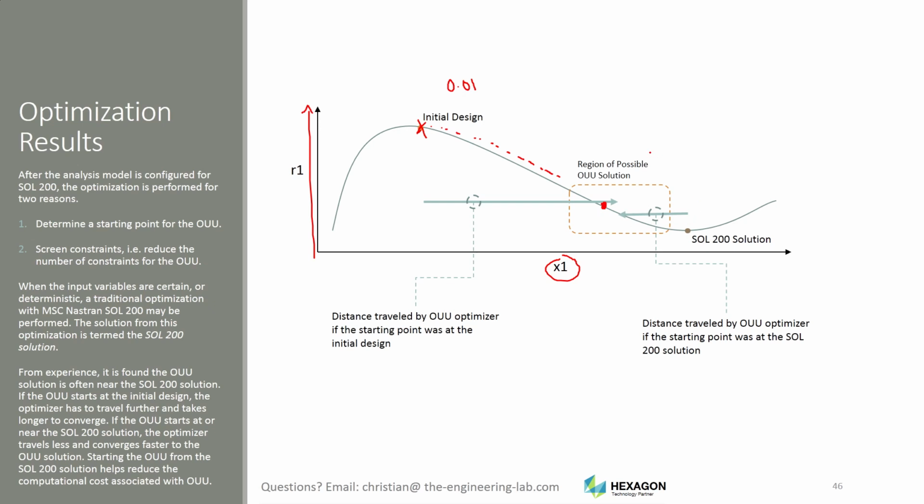We do not perform an optimization with randomness in the inputs or the outputs. We just assume everything is deterministic. There's no uncertainty. There's no randomness. We use Nastran Sol 200 to just perform a simple optimization. We vary the cross-section areas of all 53 truss members. We make sure the axial stresses are within the lower and the upper bound.